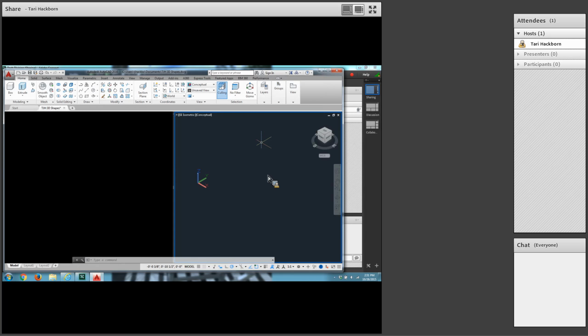Okay, to get to my layers, here's my layer dialog box, and here's layer 0, so let's get 3DM. There we are. Okay. Down at the bottom, the blue step 3 on page 49 says draw a solid box 1 1/4 by 3/4 by 1/2. So that just tells you what you're going to do. Okay. Then you have those two columns, prompt and response. The prompt column shows you what the command line is going to say, and the response column is what you will do when the command line says whatever the prompt line says to create the box.